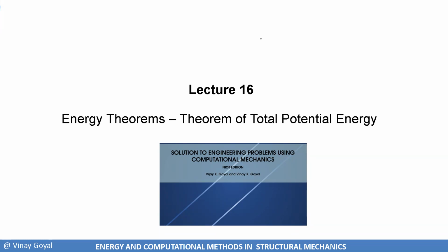And in structural mechanics, when I covered that separately, I covered the governing equations of elasticity that describe the structural response of a structure when it's subjected to loading environments. There we covered how we could develop six components of stress and three equations of elasticity that describe the equations of equilibrium, meaning when the loads are applied, the structure is in equilibrium because of these three equations.